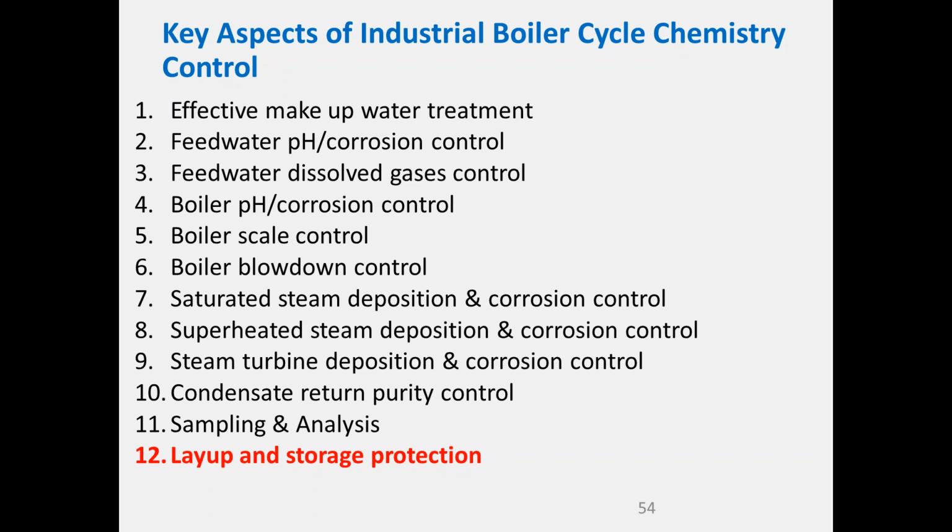has a sample cooler so that you can at least get a grab sample to do the carryover test. And we've seen a few plants built in New Zealand that have superheaters, but they never actually had a sample point installed, so they couldn't even do a carryover test if they wanted to. And that's resulted in all kinds of problems.